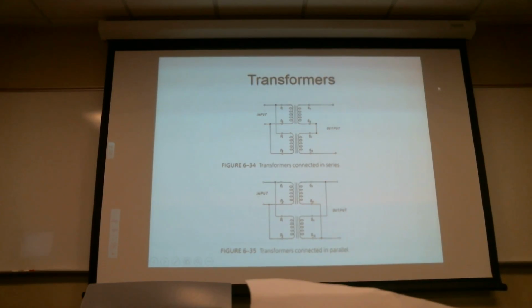And again, this is showing them as independent transformers, but in truth, I could have multi-wrapped all of that into one big bundle with just multiple taps coming out. And the taps oftentimes will be color-coded. So it's very, very common for these little AC biscuits, 2 black wires go in. Either one's neutral, one's hot. Doesn't really matter on those. On the output, you'll have a yellow, a green, a blue, or something, but you have to find the part number on there, go pull out a spec sheet on it, and figure out what all those values mean.